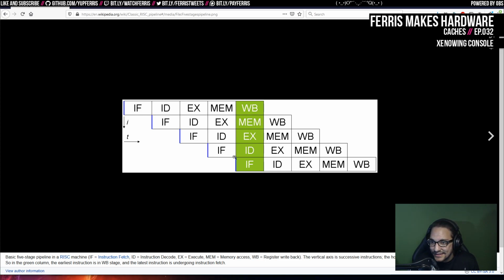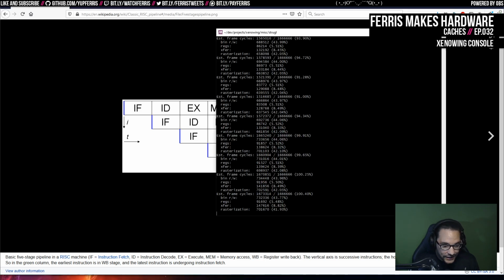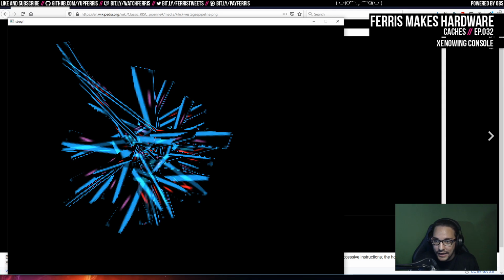So that's some of the things that are changing. I'm going to put caches around the CPU, and then I'm going to try to do proper pipelining on it. In addition, I'll do that texture cache properly, which will be really nice, and then give the GPU the ability to do DMA when it needs to. I think both of these will definitely help performance, which I haven't actually measured because I still don't have the whole pipeline, but I've estimated.